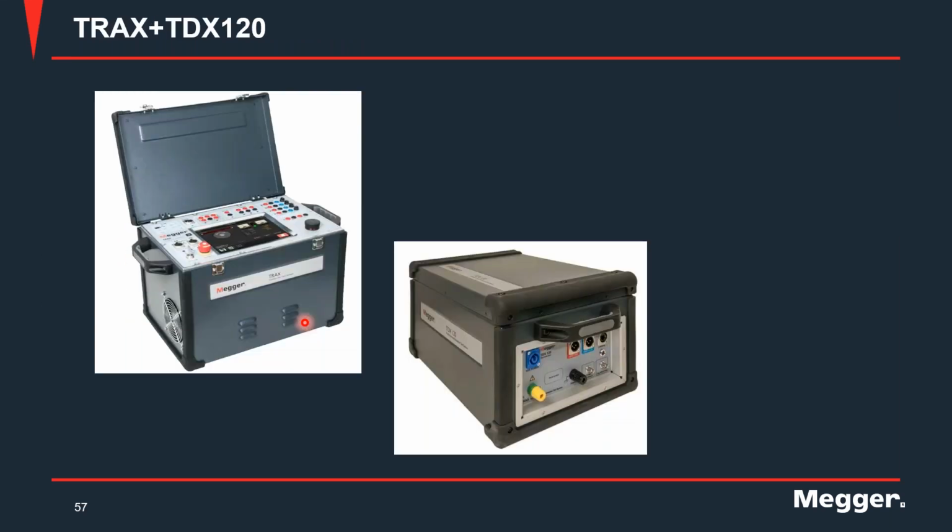Besides the Delta 4000, we also have the TRAX, which is a multifunction test set. It's capable of doing several tests, and one of those tests is power factor test. All the features that the Delta 4000 has, the TRAX has as well, or rather the TDX plus TRAX combo has as well. So TDX is the high voltage unit which actually puts out the voltage, and TRAX is the control unit or the brain of the instrument.